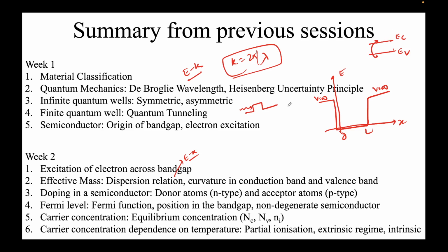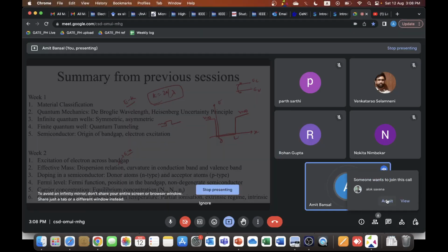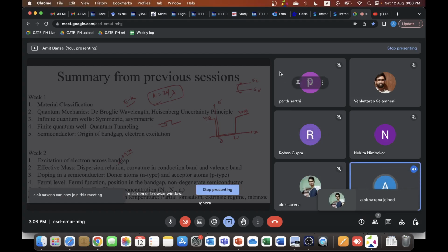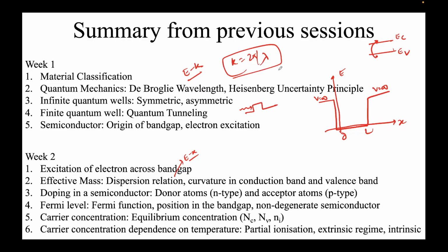Effective mass contains all the quantum mechanical information of an electron in such a system, in fact a semiconductor lattice, and then we need not worry about quantum mechanical effects so much. We can simply apply our classical mechanics expressions like F equal to m times a, force equal to mass times acceleration. In that, mass is just the effective mass, and the rest everything remains the same. Energy is p square by 2m, p is momentum, where m is the effective mass, and so on.